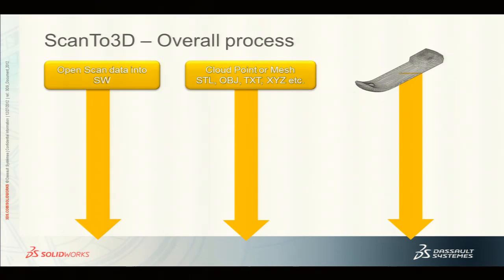So you can open up point cloud and scanned formats in SolidWorks. If you have Premium, you first click on the add-in Scan to 3D. Another very important point is that you don't want to use the regular file types. When you open up a point cloud or scanned or mesh object, you have to drop down in the file type to the Scan to 3D types, because that reads it in a special way that you can use it. Just remember that. I'll show you that later.